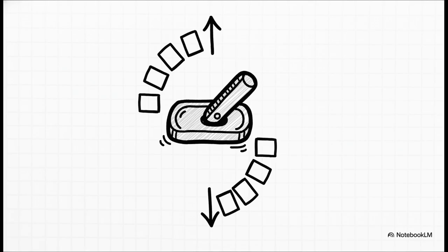But the real elegance is in the up/down counter. By adding a simple combinational circuit between the flip-flops, engineers created a mode control input known simply as M. It is brilliantly simple. If M equals 1, the circuit counts up. If you switch M to 0, it instantly reverses direction and counts down.